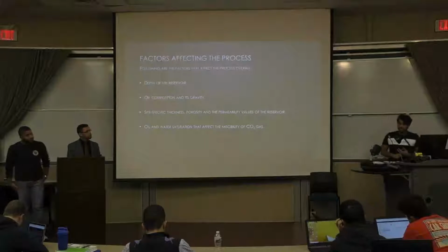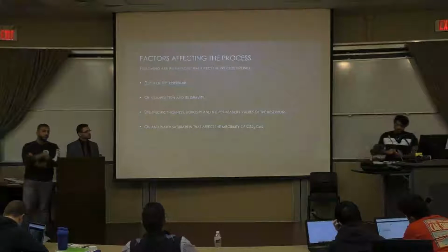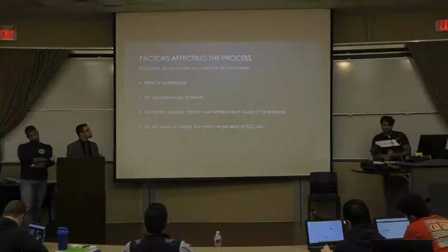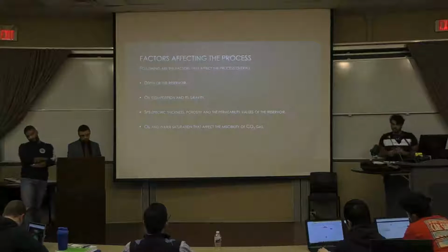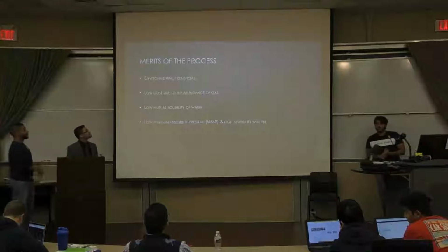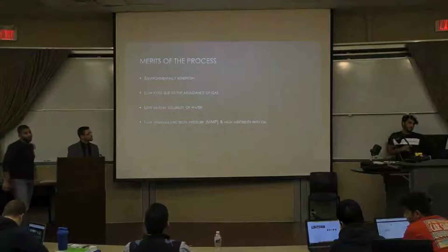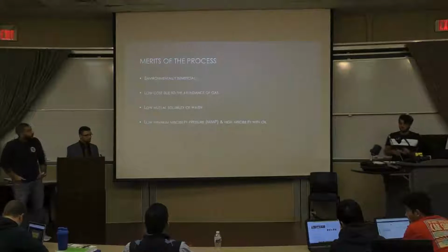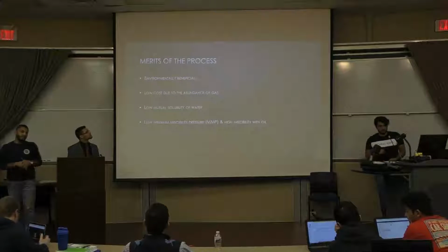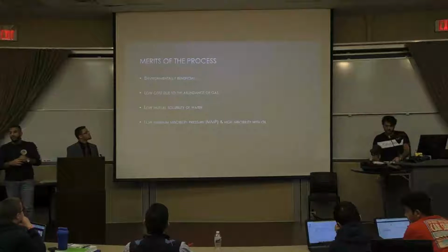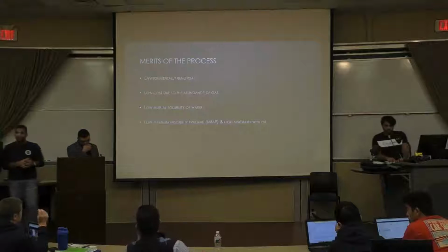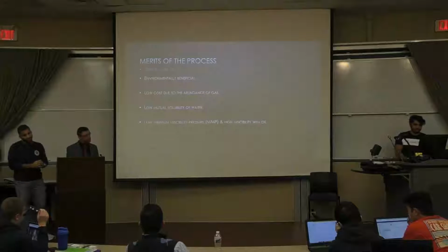This process is simple and economical because CO2 as a solvent is cheaper than other miscible lower hydrocarbon solvents. This process has some merits, and one of them is that it is environmentally beneficial if the industrial CO2 is captured and stored in the reservoir. Low cost due to the abundance of gas, low mutual solubility of water, low minimum miscibility pressure, and high miscibility of oil.